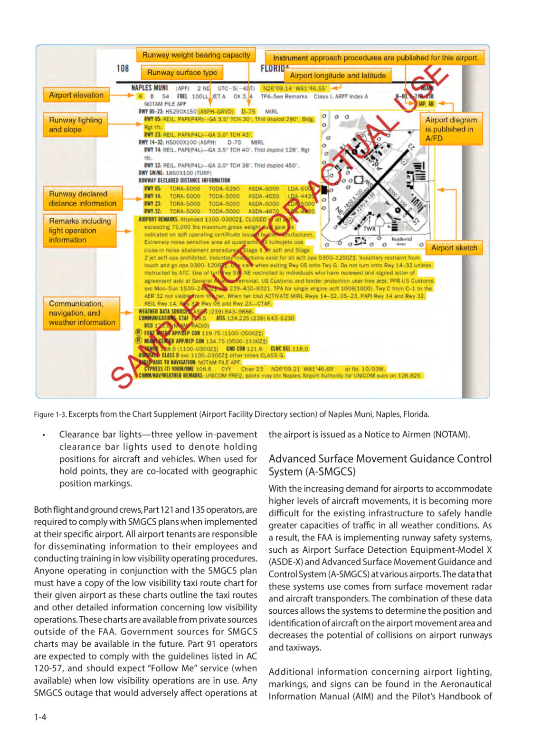Part 91 operators are expected to comply with the guidelines listed in AC 120-57, and should expect follow-me service, when available, when low visibility operations are in use. Any SMGCS outage that would adversely affect operations at the airport is issued as a Notice to Airmen, NOTAM.